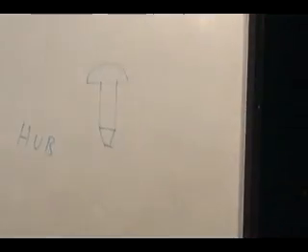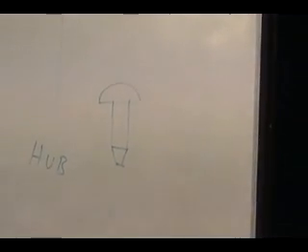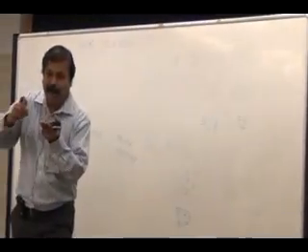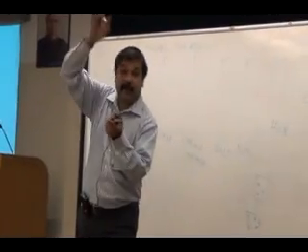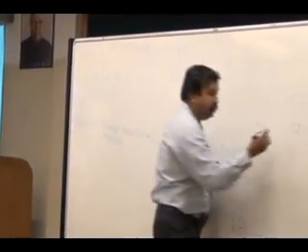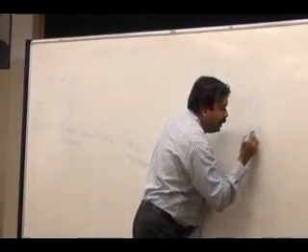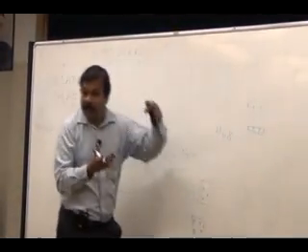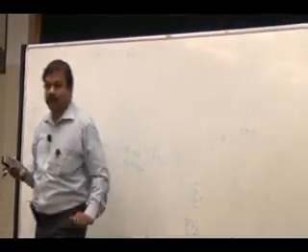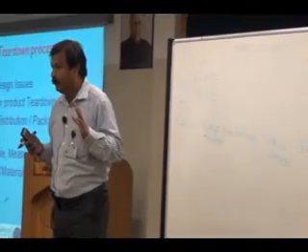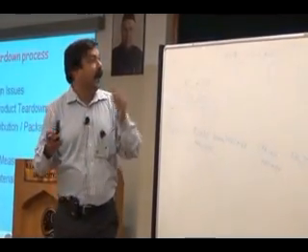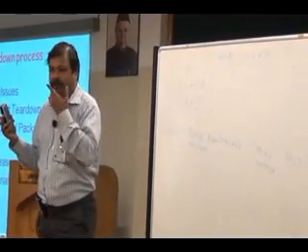What they will do is keep this blade holder here, put the rivet, hold it at the bottom, and then no screwing. They will hit it hard so that this part will deform, and the blade and the blade holder are caught in between these two. Are you able to understand what I mean? Like bolts and nuts, like welding. Riveting is a metal joining process.